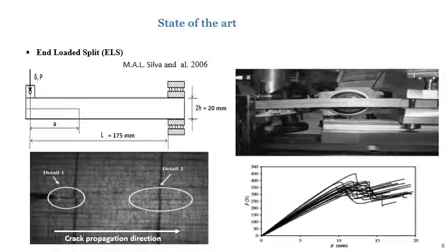Nevertheless, it requires a rather complicated assembly to maintain the conditions of the sliding embedding. Several researchers have used this setup, including Silva et al., who adopted this model to try to solve the problem of crack tip determination. In fact, Silva used 19 specimens of Pinus pinaster wood with a moisture content of 12% and an average specific density equal to 0.57. The notch was introduced using the same method as described above.